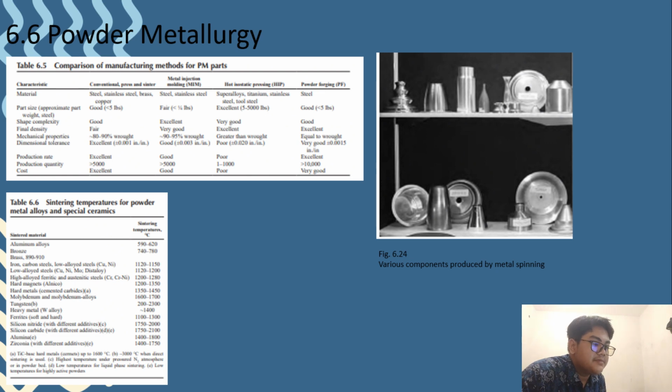Fabrication of parts by the PM method has several advantages that include: A, producing parts with more uniform microstructure and distribution of alloying elements. B, high volume production of parts with net shape or near net shape dimensions, thus reducing the need for machining. C, flexibility in component design. The design flexibility with PM is quite remarkable in the production of parts with many grooves, tapers, curves, and multiple level gear assemblies.